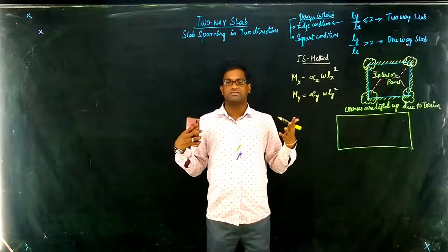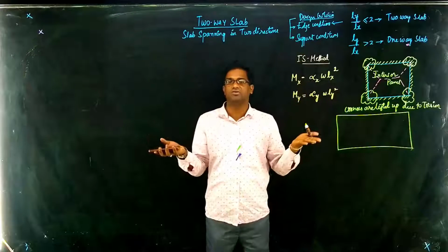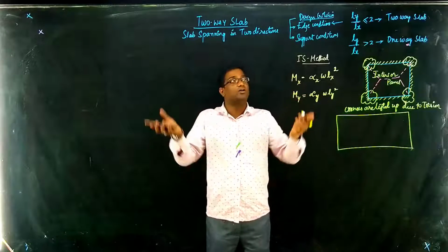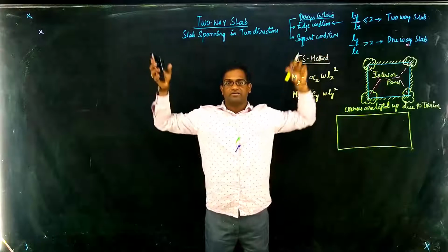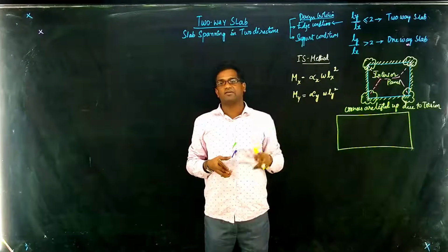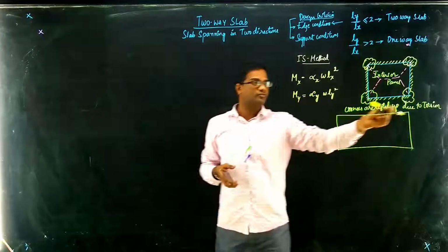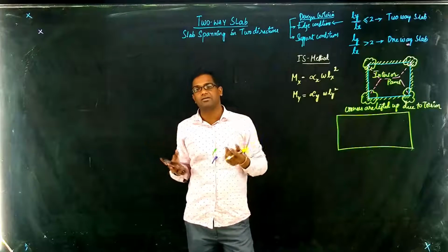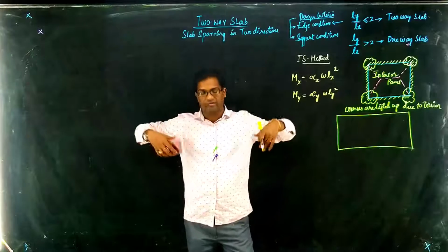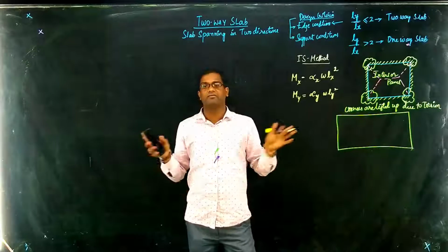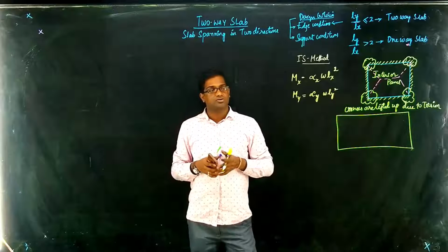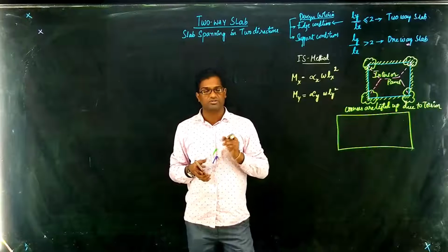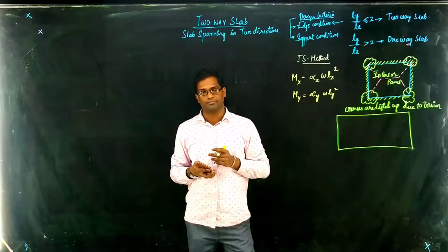You know, imagine a slab totally falling down. The slab will be in a good position, but the slab comes off because of the cracking in the corners. If this is happening, then the slab has failed due to lack of provision of torsional reinforcement at the corners. The slab has excessively bent, the cracks have developed at the corners, and it totally fell off. So this can be avoided by providing additional torsional reinforcement in the corners, which is also given in the code.